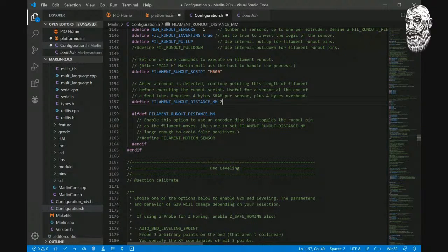So basically, it's just a safety switch. Like maybe a wire got a little jiggly, or there's a small break in the wire. Those small breaks won't cause a physical runout script to happen. It won't actually stop printing, move the nozzle over, eject the filament, and wait for you to enter new filament. It'll be like a blip and be like, fine. With this safety feature, it'll blip, wait for you to print 2 millimeters more, and if it's still off, it'll then trigger the M600.